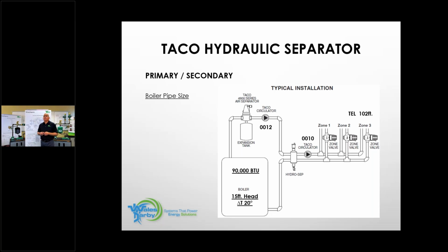The system side, I guess we're going to stay with the same BTU, or are we going to adjust the delta here, John? What do you want to do? Give me 20. All right, so same 20-degree delta. Okay, so it's 9 GPM. Your longest loop is 102 feet. There should be no math involved there, guys. You know where that's going to be.